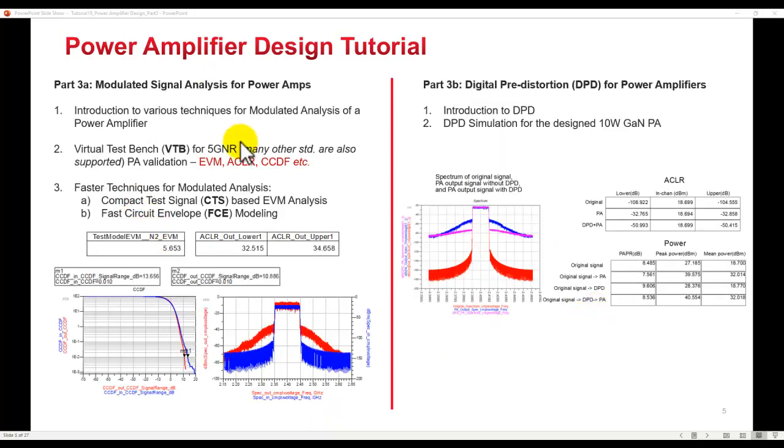Now in this current tutorial, we will look at ways and techniques to perform modulated signal analysis because no matter which standard you might be building the PA for, it's unlikely that you are building a PA for CW operation. May it be a 5G, Wi-Fi or radar application, every standard will have some kind of modulated signal over which your PA has to be operated.